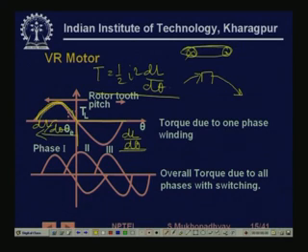So, over a rotor pole tooth pitch, the torque generated varies like this. Now, how are you going to switch the phases, and when? Initially you switch phase 1, so this rotor torque is positive. The rotor moves and then the torque will fall.